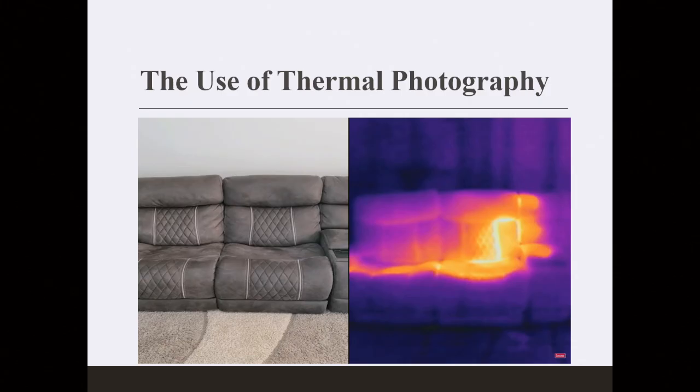So think about using thermal photography. What is the major property that can tell you that the concrete is of good quality during fresh concrete mixing? Is the hydration of cement exothermic or endothermic? It's exothermic, right? Once you add water and cement, once the hydration starts, heat is released. Based on the amount of cement, the amount of water, and the water-cement ratio, which basically controls your strength, you'd have an equivalent heat being evolved.